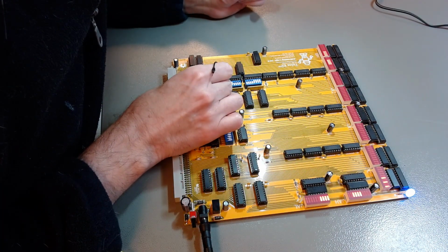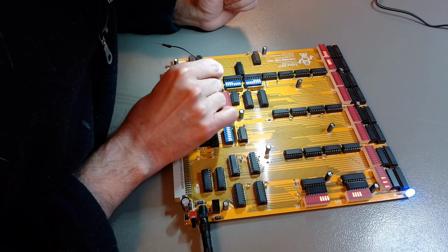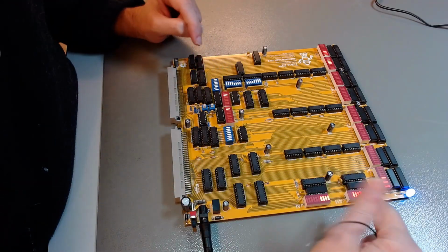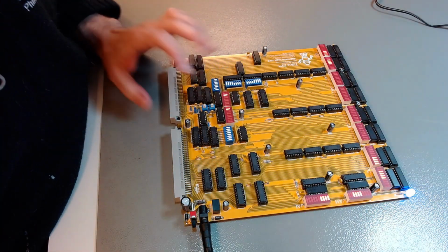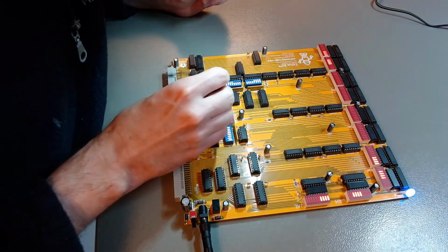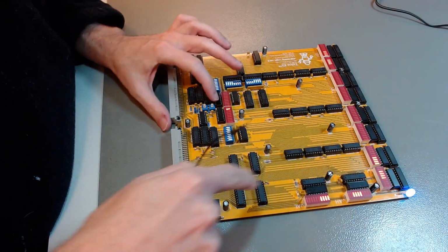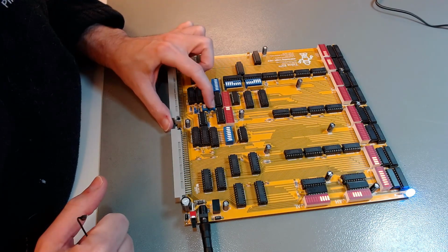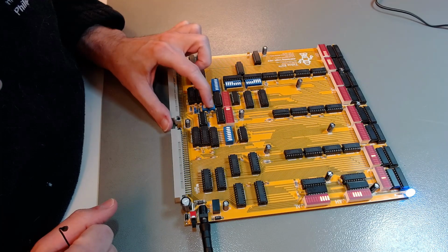So now I will disable the load of the jump address register, and I will enable the program counter load. So program counter load enable is now active. When I press clock, this value should go into the program counter, overruling the count I already have there. And there you go. If I press clock again, nothing would change because I still have program counter load enable. But if I disable the load on the program counter, the value will stay there, and when I press clock, it will continue to count from where it is now. And indeed, that's what happens. See, it even counted across the 2 bytes. So that's a good test.